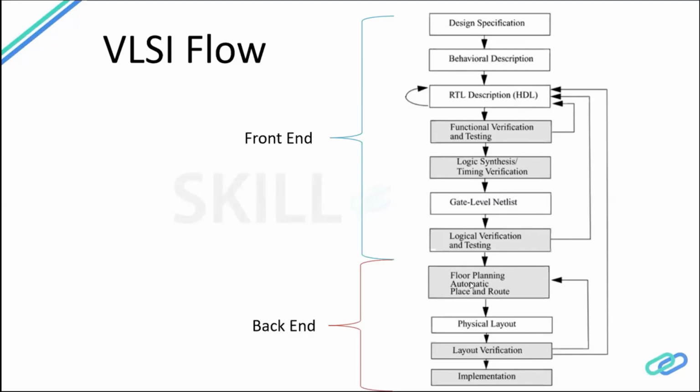Floor planning is where, on a die, we place each component depending on what kind of component it is, whether it is high power driven or requires more power, and how the components are used, for example whether it has more input ports on the periphery of the cell. So we place it near the boundaries. Similarly, output modules we place at the output side.